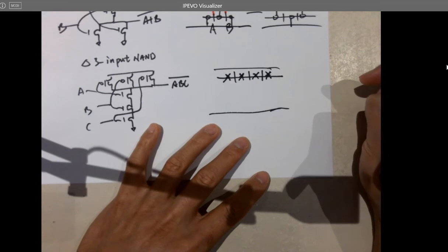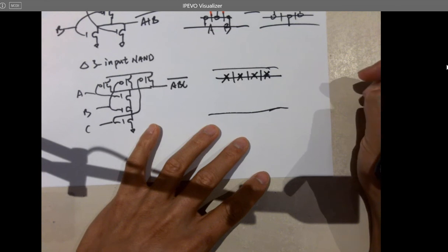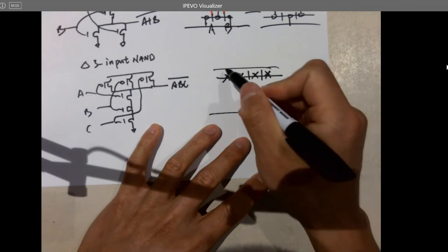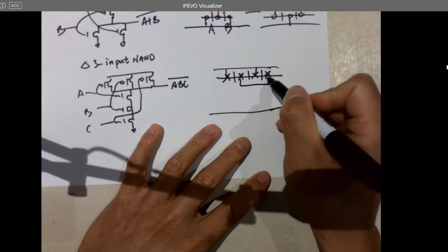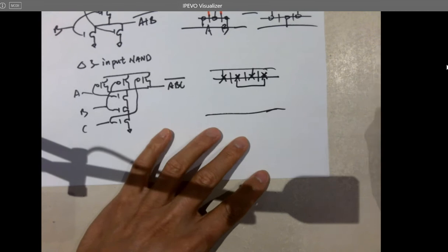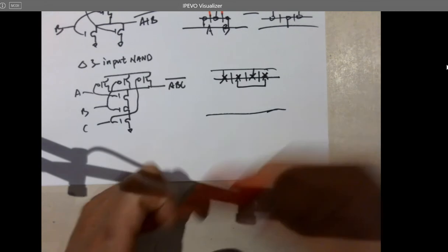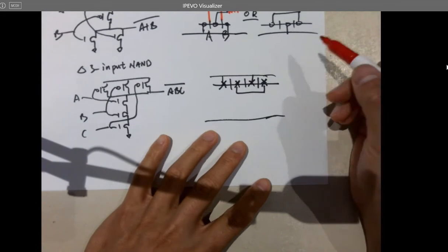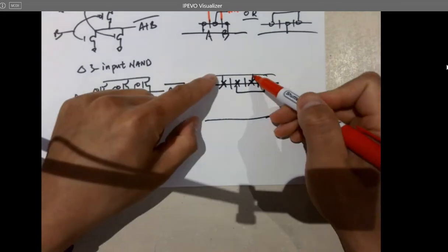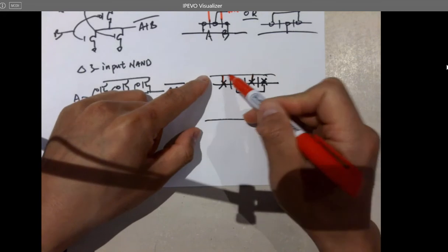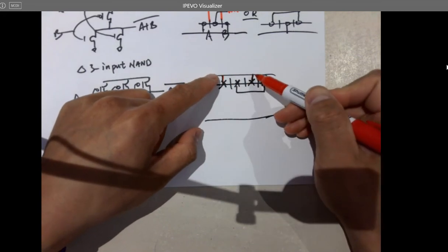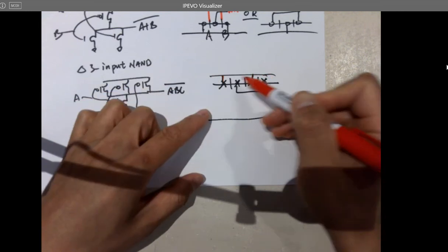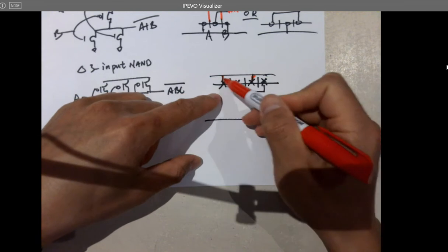And they're in parallel. How do we make it happen though? One here, and one here. And why? Why is this 3 parallel PMOSes? So these 2 wires are being shorted to the VDD, the top rail. So you can consider them as one voltage node. It's just one metal piece. And it's going to introduce currents from VDD at the same time.